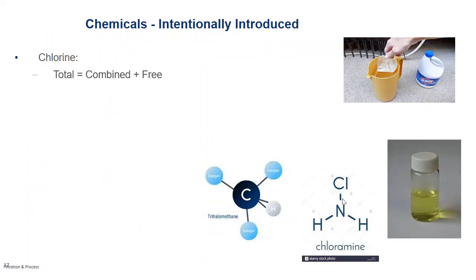When you walk into an enclosed swimming pool environment, that chlorine smell you're getting off the water is actually chloramine. This is a nasal and eye mucous membrane irritant. It's the reason your eyes get red and your throat gets sore after swimming. But this is also an effective sanitizer. Not as effective as bleach, but it lingers in warm water supplies longer.